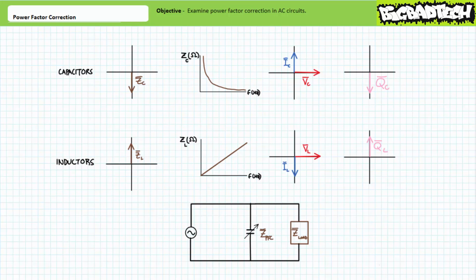In summary, a power factor corrected system will draw less source current, yet experience the same amount of real power. This is the single most fascinating aspect of power factor correction, and the reason why it's one of my favorite subjects. By balancing the reactive power requirements internal to the circuit, you get the same results for less input.